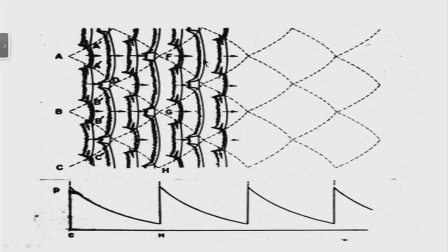As it keeps decaying, the induction time, I show the zone of chemical reactions by a black line over here. This is the zone of chemical reactions between the shock front and the chemical reaction. There is a zone or induction time, the time taken for the reactions, and as the shock decays, this tends to decouple from it, and then this shock further decouples, it becomes an incident wave, and it further reduces in strength, and therefore, I have totally decoupled reaction, but then the transverse waves come and hit at this point wherein the triple point intersects and a new Mach wave is generated.